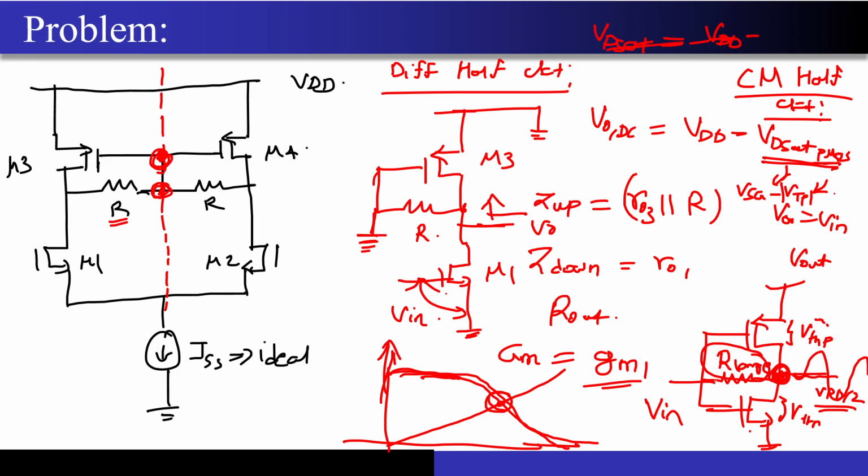So now what we did was we inserted a huge resistor between the input and the output. What it did, it enforced the condition that the input and the output will always be equal. I'm talking about the DC point over here. So now if the output and the input's DC point is equal, this is where I have enforced the condition. This is where I have fixed my operating point now. Any small signal that is present around the VIN, around this particular range, now the bias point is fixed. The bias point is now not poorly defined.